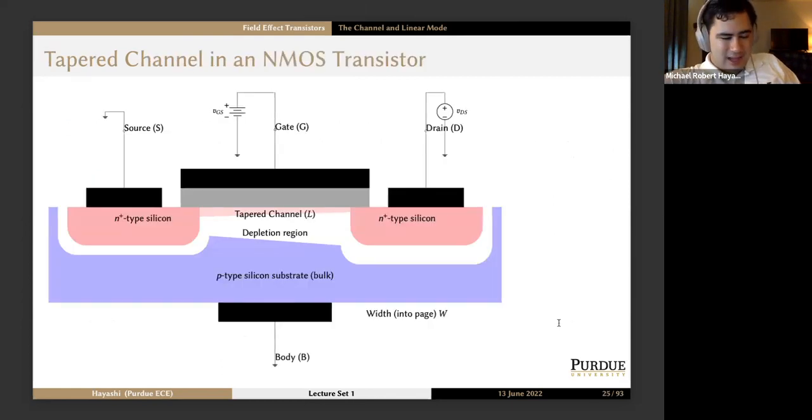So now I'm going to read to you from slide 26 while leaving slide 27 up. So what happens if we apply a big VDS when we have VGS in place to create the channel? Well, what's going to happen is the gate to drain potential is going to be smaller because if you go around a KVL loop, ground plus VGS minus any voltage drop in the device itself minus VGD equals 0, we see that there's less gate to drain potential here.